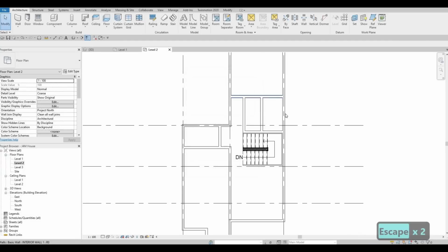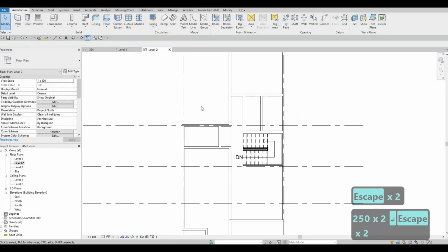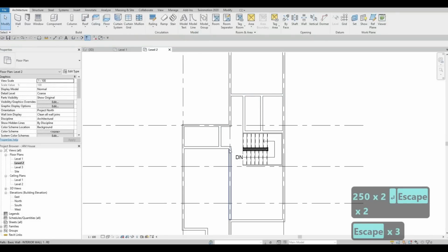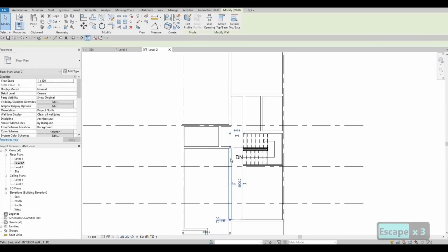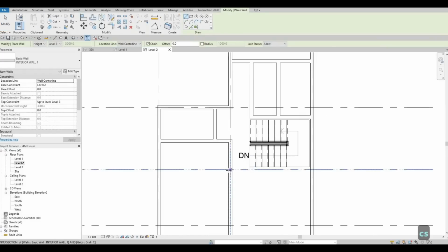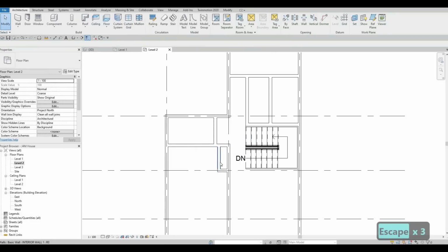Make it 25 at least, so that everything is uniform in terms of length. And then here we're just adding an indentation so that it's not crowded. So here probably 400 from the CS grid, and then here, or we could just align it from here.